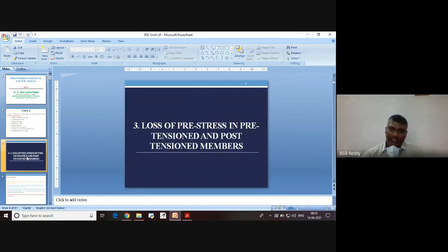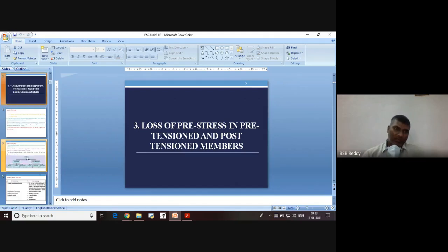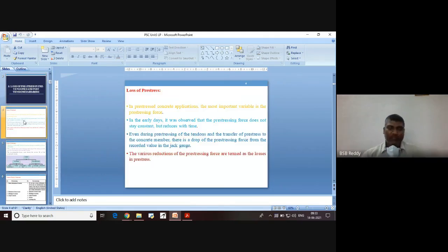Okay, right. Let us now talk about what are the losses that occur in pretension members and what will be the losses in post-tension members. Or else, what are the losses of pre-stress which occur immediately, and what are the losses of pre-stress that occur over a period of time. So there are two such categories.